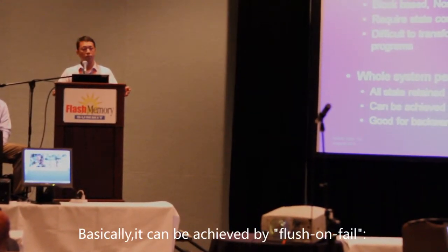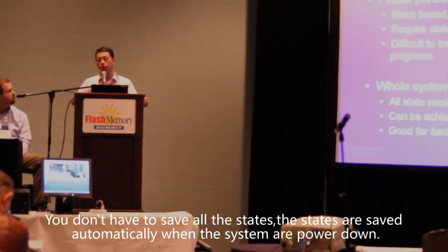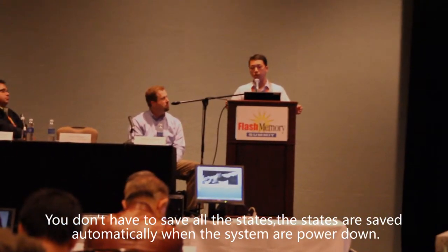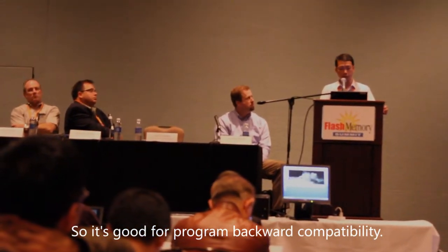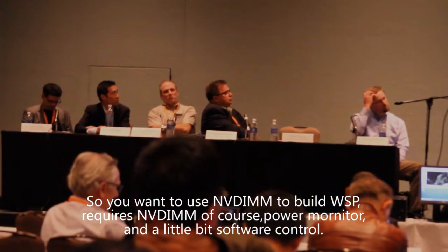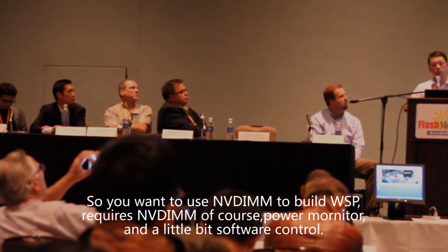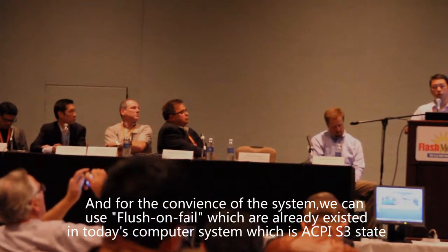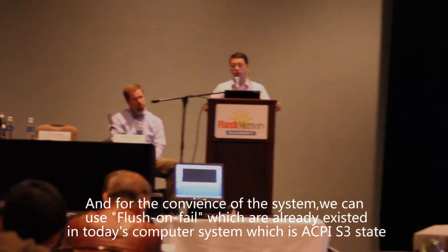Basically, it can be achieved by flush and fail, where a power loss event occurs. So an individual program doesn't need to save all the states. The states are saved automatically when the system is powered down. So it's very good for program backward compatibility. In order to use NVDIMM to build a WSP, it requires NVDIMM, of course, and then a power monitor supply and a little bit of software control. And for the convenience of the system, we can use flush and fail, which already exists in today's computer system, which is the ACPI S3 state.